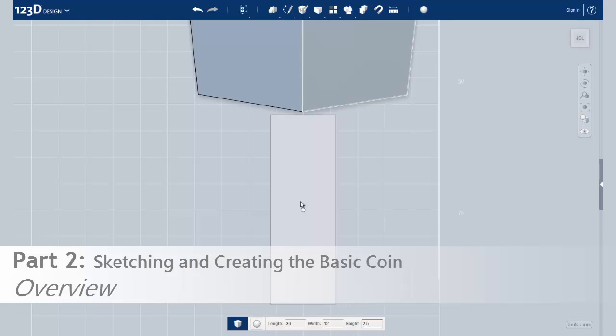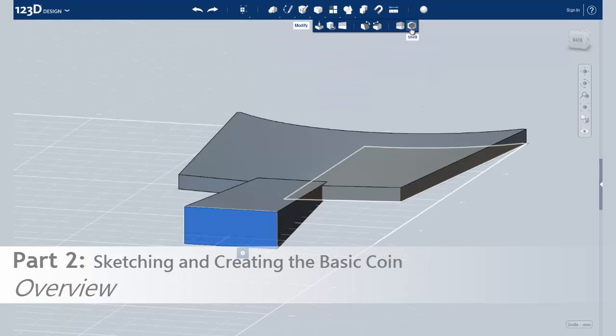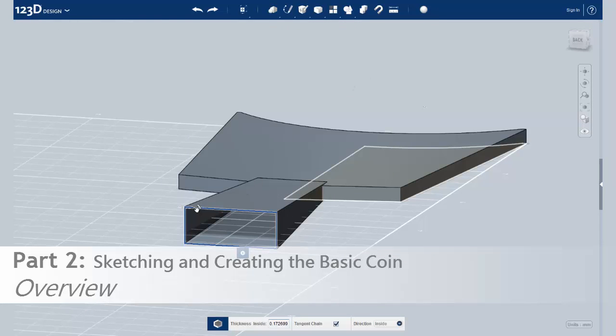We will use a primitive box, manipulate its dimensions, and then we will pull the edges of it to give it a pyramid-like shape using the tweak tool. After that, the handle will be hollowed out using the shell tool. Alright, let's get started then.